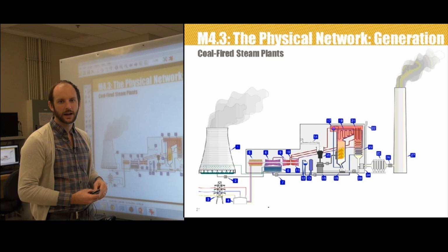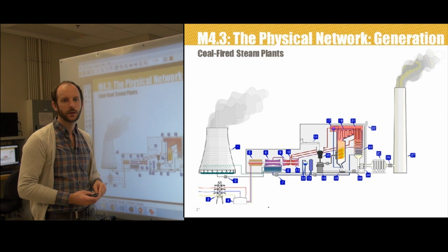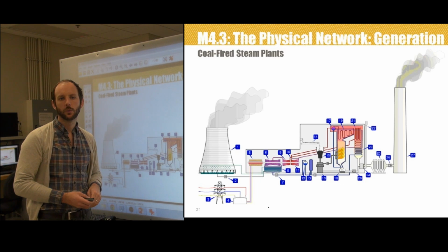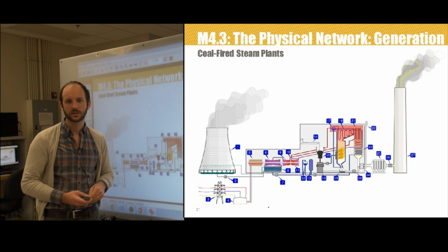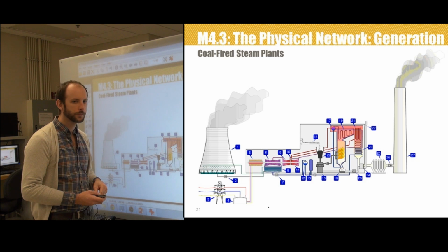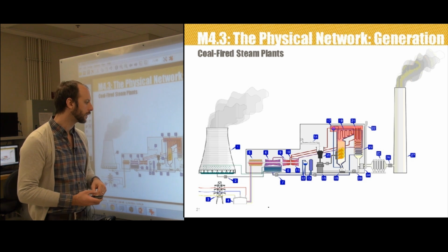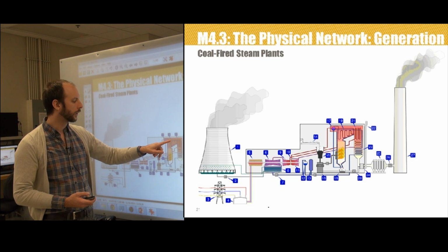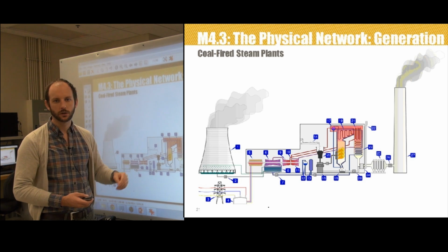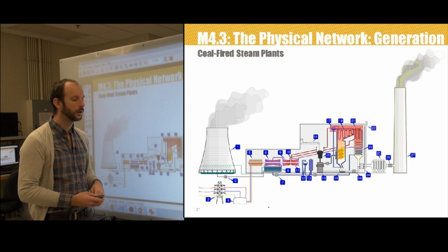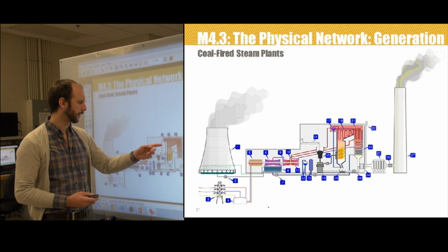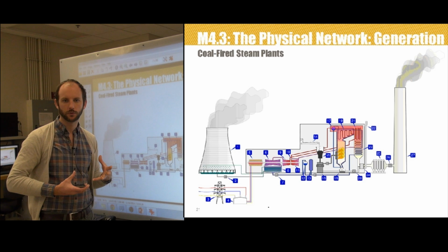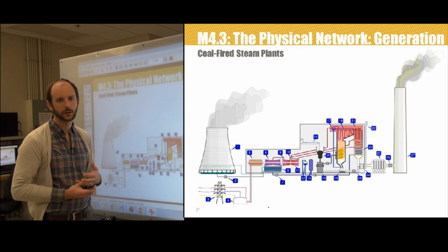The steam is going to pass through the manifold in the roof of the drum into what's called the pendant superheater, number 19 here, where its temperature and pressure are increased rapidly to around 200 bar and 570 degrees. So there's high pressure, high temperature steam flowing in these steel tubes here, still inside the boiler. And it's actually hot enough that you can see these tubes light up a little dull red color from the heat that they're carrying.